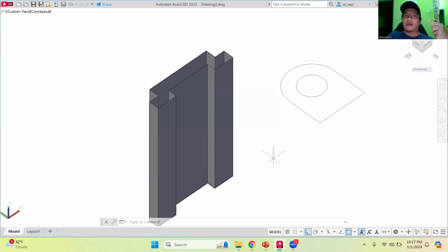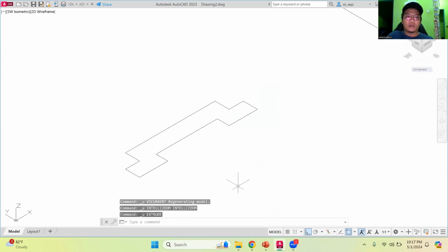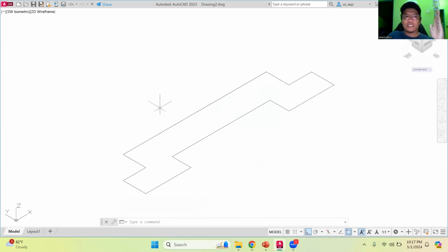Another thing is, there are a lot of situations where, I guarantee, this will happen to several of you. Let's say you told me that you have joined your lines, right? You told me you have joined your lines. You know what? Let me undo first. So remember, if you extrude a line, even one line, it becomes a plane. So you have to join these lines.